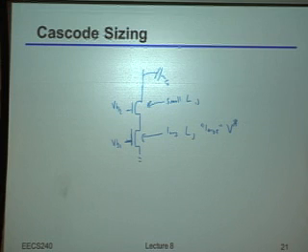But how about V star? What are you typically going to choose there? Yeah, you're probably going to choose a reasonably small V star. Why is that? Yeah, exactly. Your noise is going to circulate anyways, right? And you probably want a reasonably high GM for the same bias current. Now, there's obviously a little bit of a trade-off here, because if you make the V star too small, you'll have a lot of parasitic capacitance. In other words, the FT of that device will get too low. But again, that's why I put things in quotes here.